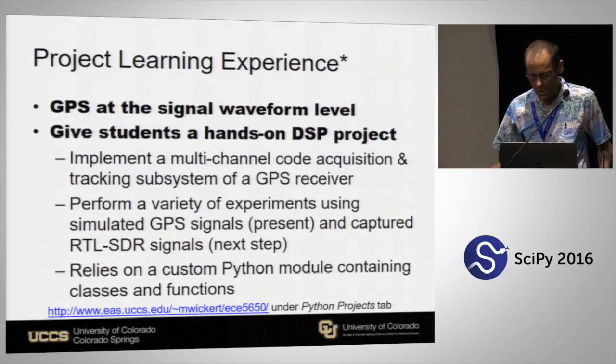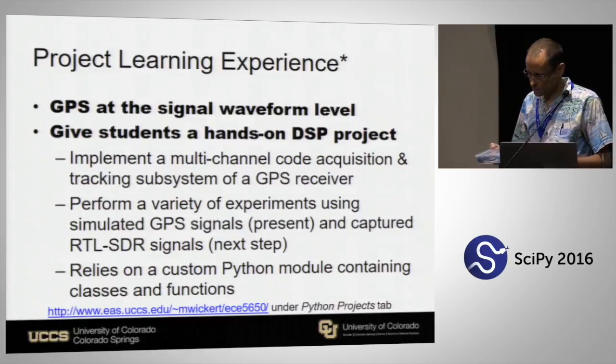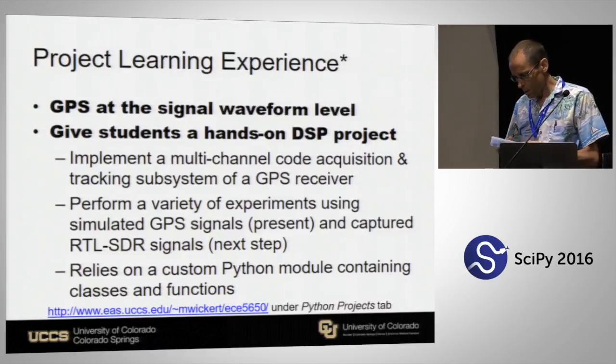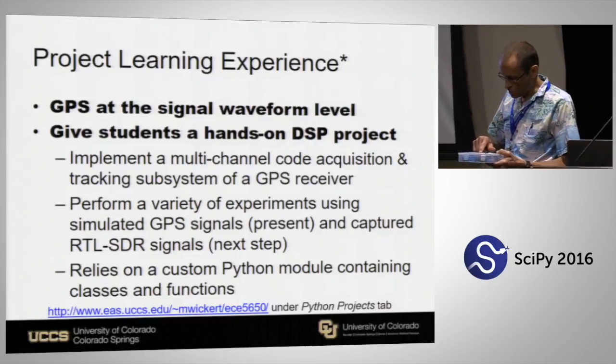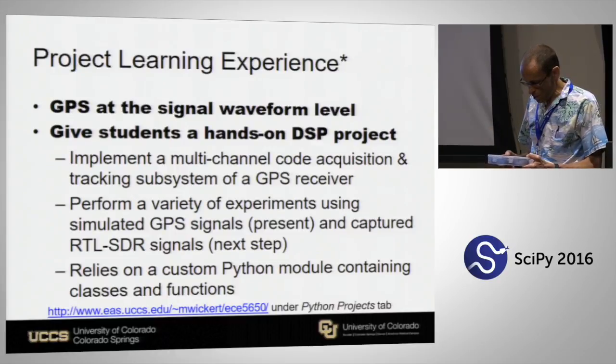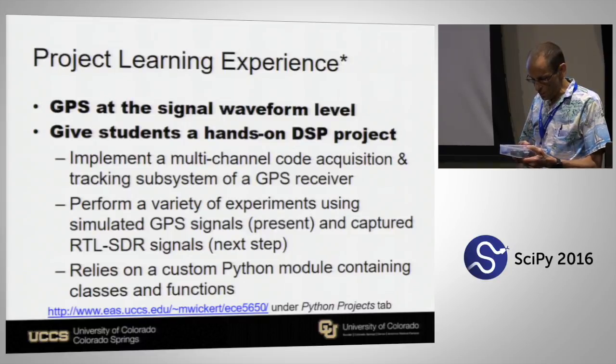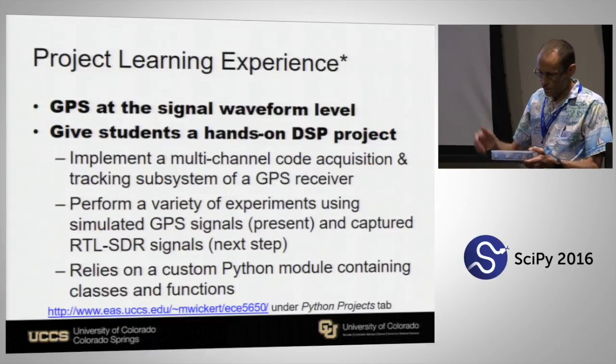So the next step would be to go into a software-defined radio setup, and that's what I've got in this box, a front end I can put on, and I can use in Python, I can use in other environments. It's the RTL-SDR. It's in the blue box in here. Then there's a GPS patch antenna in the black square, and then it's a preamp or amplified patch antenna, so then I had to make what's called a bias T to send a voltage up the transmission line to power the preamp and the patch antenna. And then there's a black battery case.